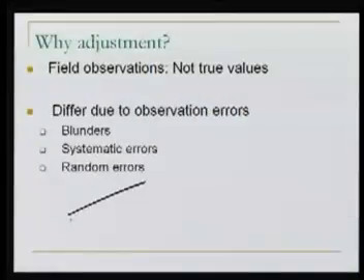We have seen this. Now the errors, as we can see here in this slide, we define in 3 categories. Number 1, blunders, those which can be detected by some statistical method. Blunders means they are very far away from the main group of values or observations. We can scan the observations, we can find there is something wrong with this particular observation, so that's a blunder. There are methods of detecting those, eliminating those.